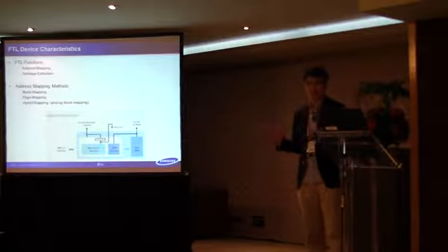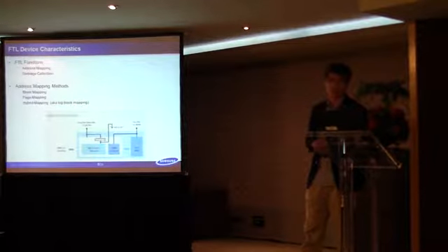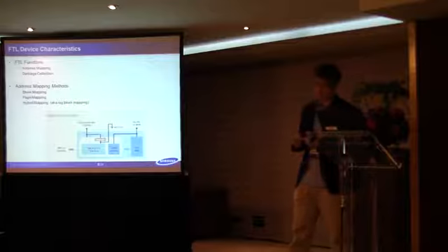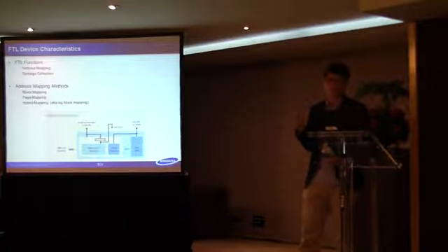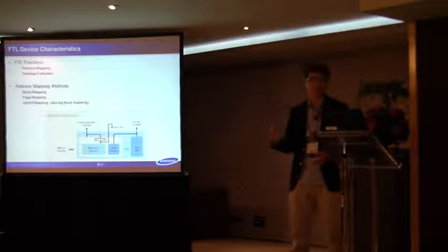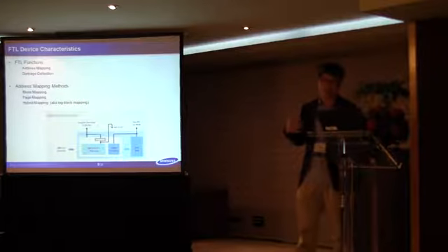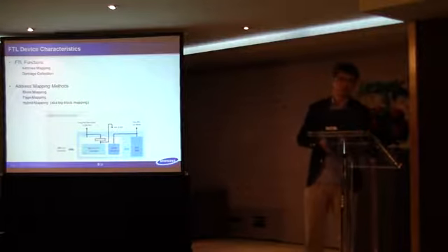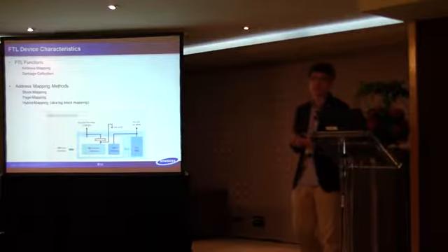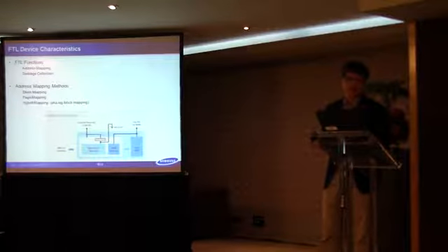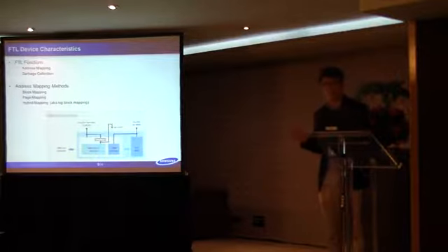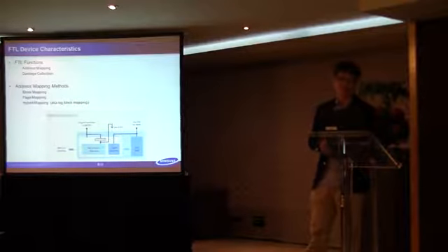In every write operation, the flash block is written again with only a small change inside it. So only a page is updated, but all the block's pages are retrieved from the storage and written back again after erasing. That causes a major performance bottleneck. So I think block mapping is not well used in most storage devices now.